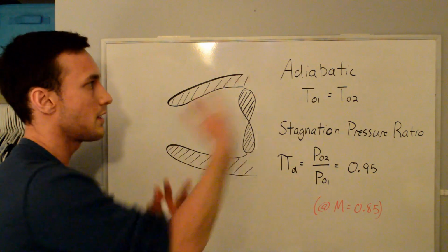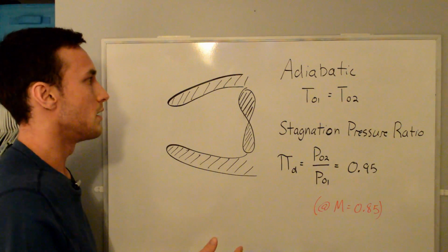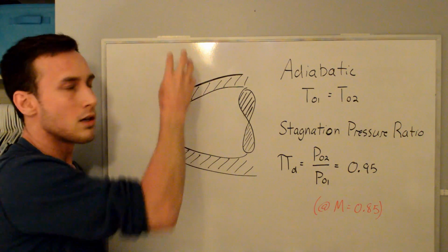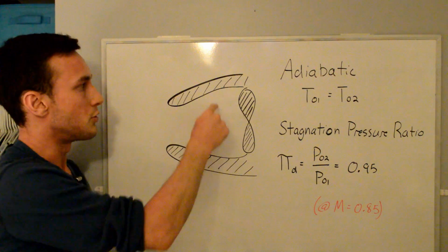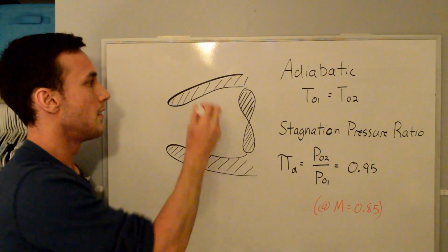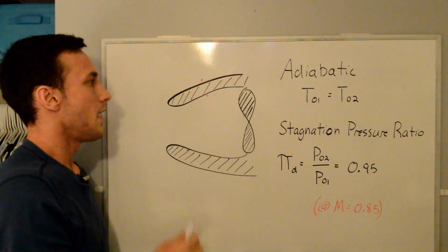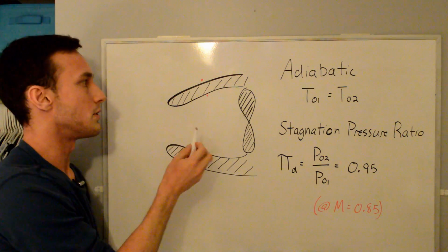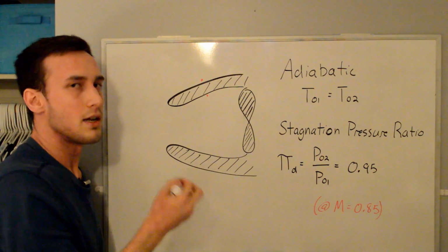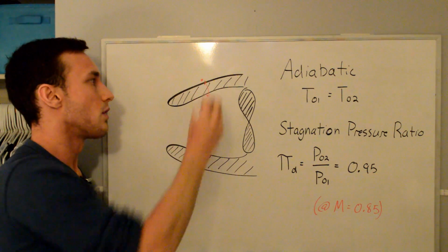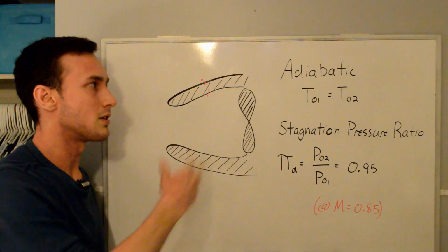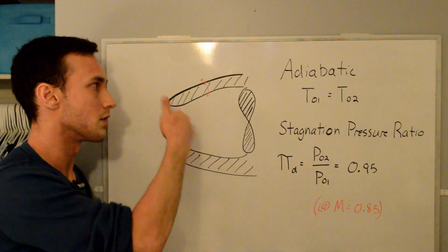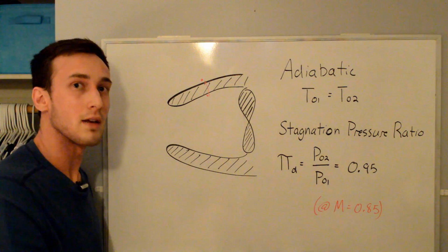And so let me just step back 1 second for the adiabatic assumption, and the reason you can assume it's adiabatic is because the heat loss depends on temperature gradient. So the temperature difference between, let's say, a point that's here and the point here. And if you look at it, we can assume that there's not really a big temperature difference between here and here, and so we can assume that there's no heat loss through this wall here. So that's why we can make this adiabatic assumption, but we can't make the reversible assumption because there's always going to be friction losses in here, maybe separation, that kind of stuff.